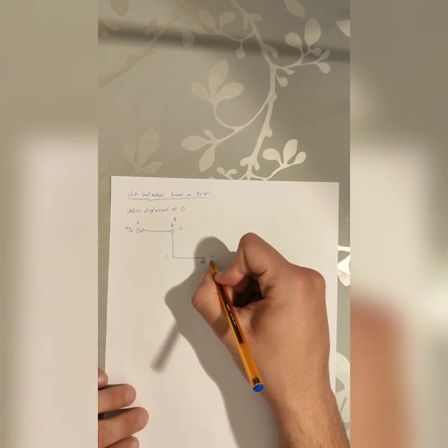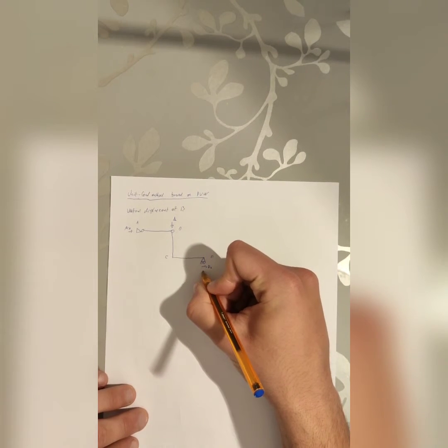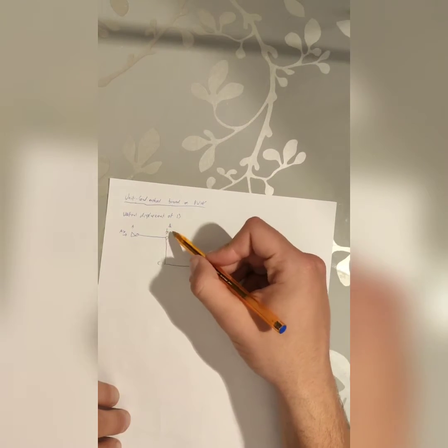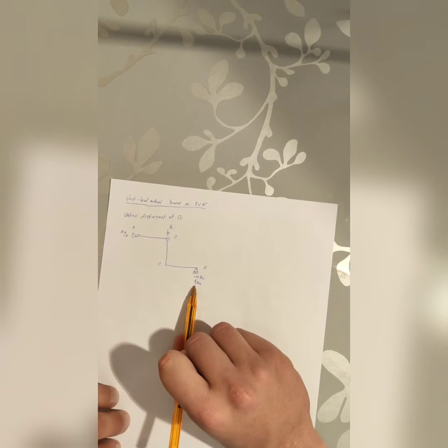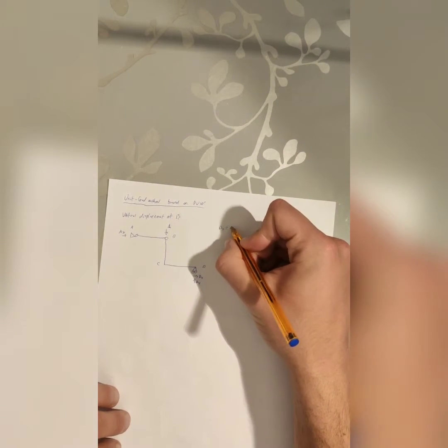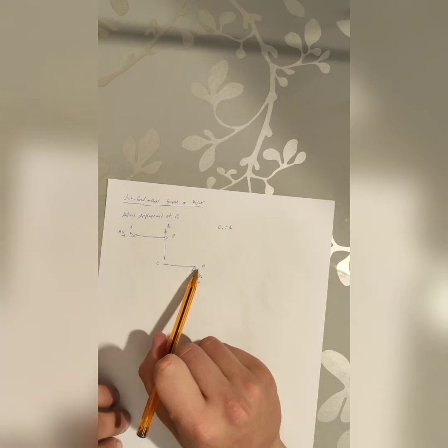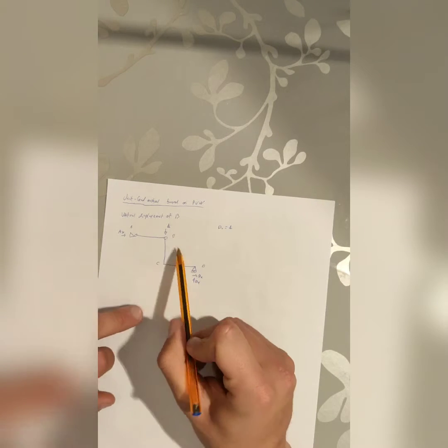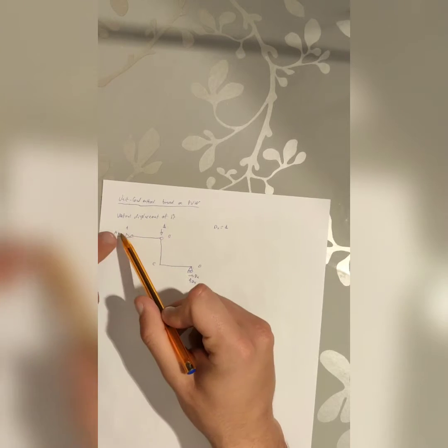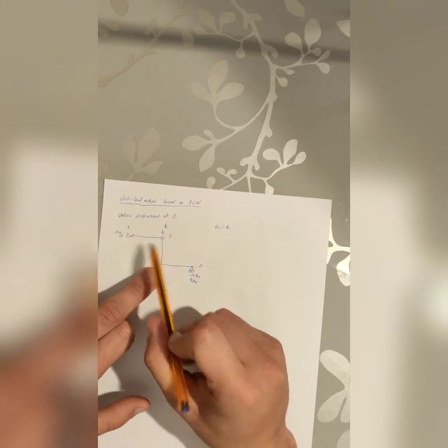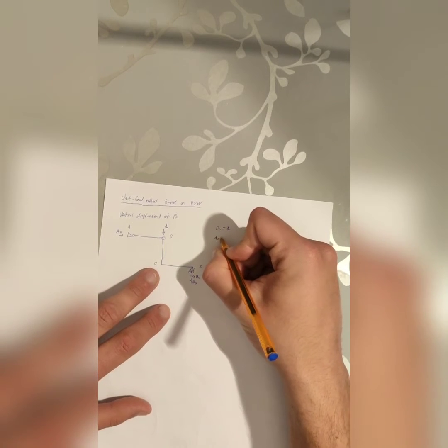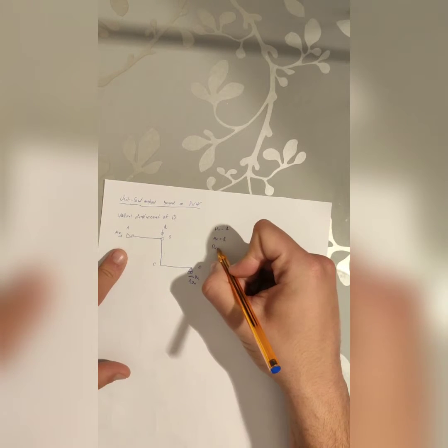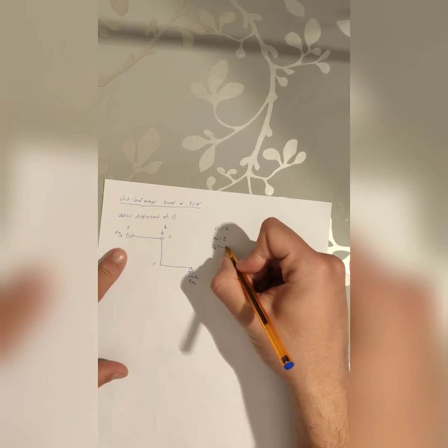AX, dx, and dy. Just applying the equilibrium equations, we can see that in the vertical direction 1 and dy, it means dy equals 1. Applying the equilibrium of moments at point D, we have 1 times L on this side and AX times L on the other side. Therefore, AX has the same value, 1. And finally, if AX is 1, dx is minus 1 from the equilibrium of the horizontal forces.